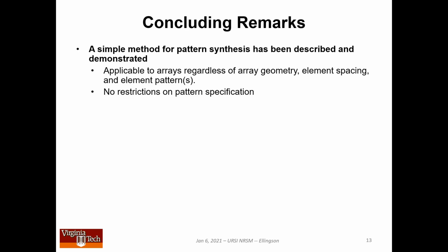So here are some concluding remarks. A simple method for pattern synthesis has been described and demonstrated. This is applicable to arrays regardless of array geometry, element spacing, and element patterns, and there are no restrictions on the pattern specification. Also, I should note that I think it is unlikely that this method is truly novel, since the derivation is very simple and is a somewhat obvious thing to try once the problem is posed.